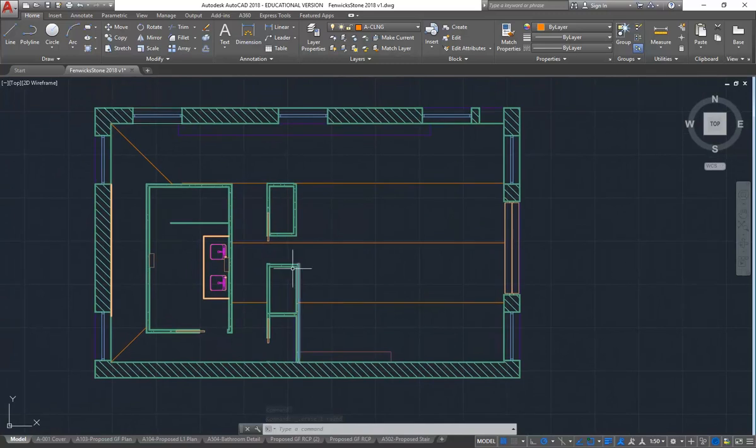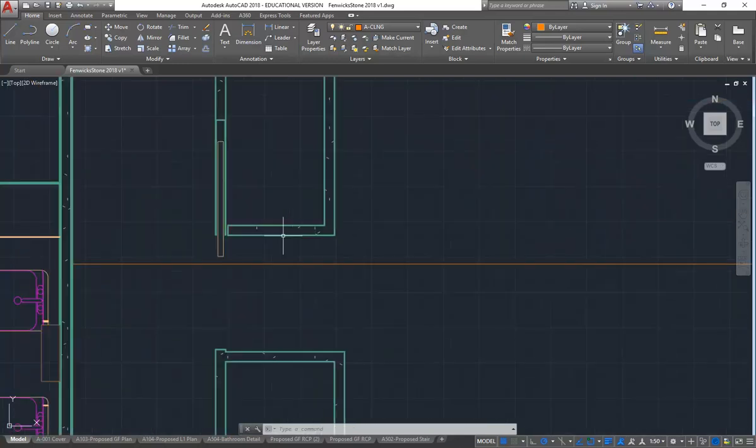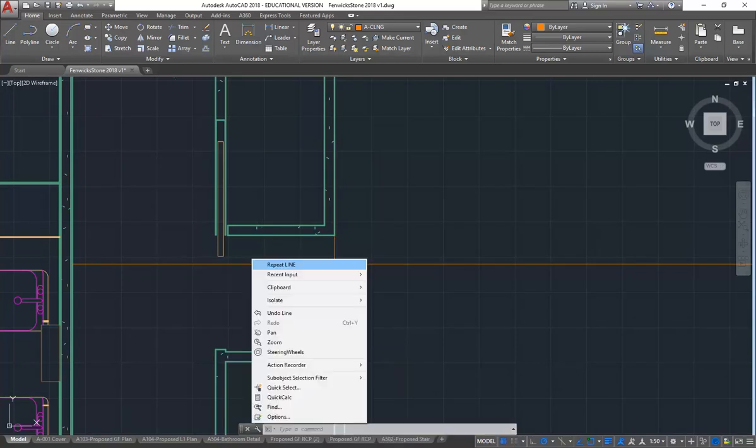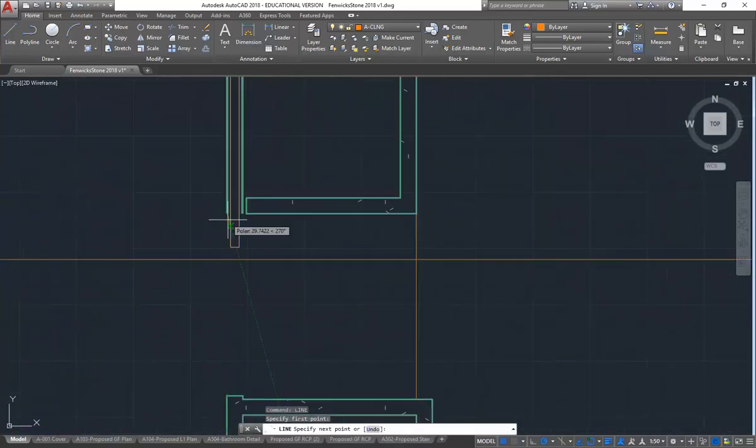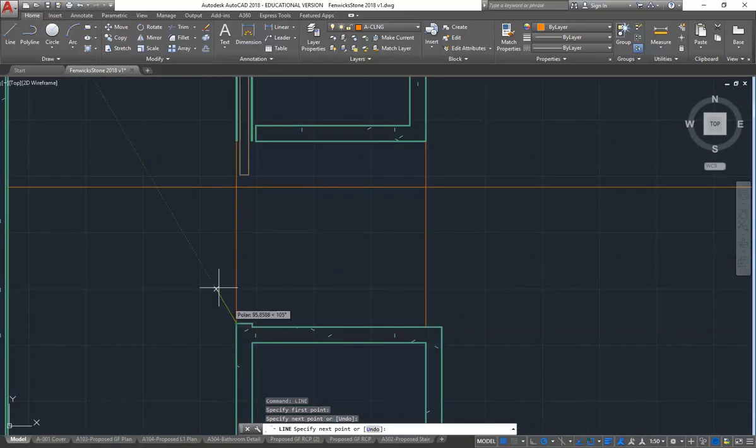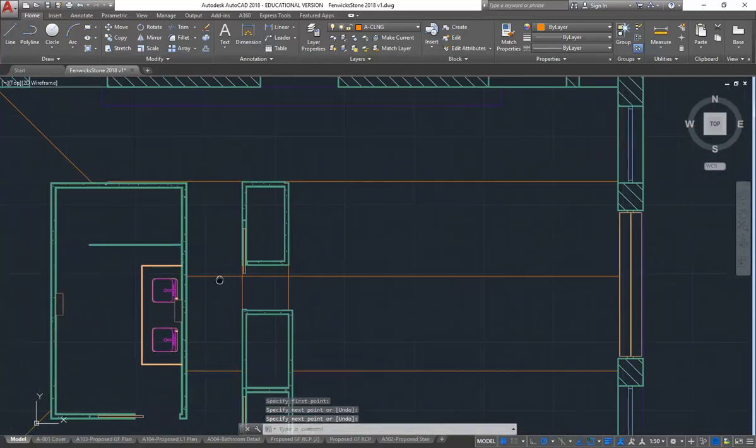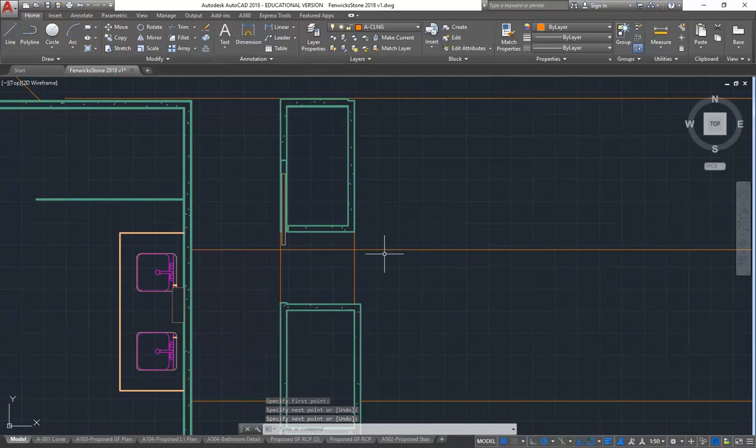Okay, so again, just thinking about what we'd see. So if this is a cupboard, which has its own little cupboard top, which effectively is acting like a ceiling, then again, in a reflected ceiling plan, we're not going to see that. In other words, we're not going to see the ridge because the little roof of the cupboard will block that.